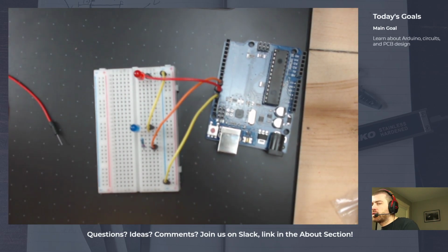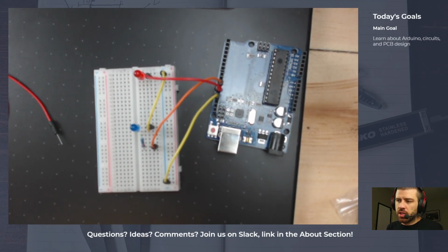because an LED can only handle so much electricity. And so this is one of the things you might actually find in terms of safety. LEDs can only handle so much electricity, so you always want to use a 220 ohm resistor to kind of limit the amount of power going through the LED. Because if it gets too much, it kind of heats up and it'll burn out. I've seen them kind of crackle or pop. It's not the worst thing in the world.